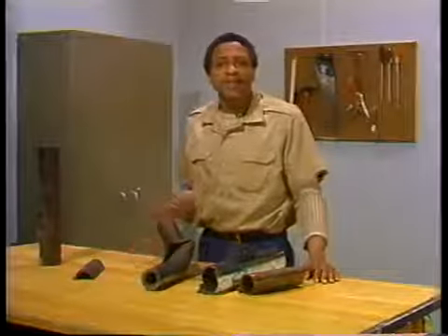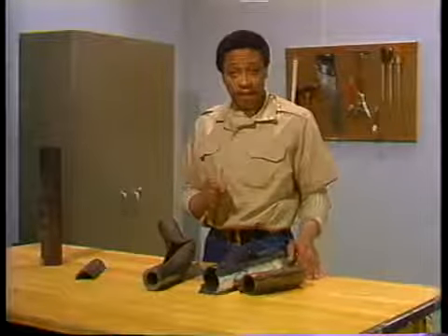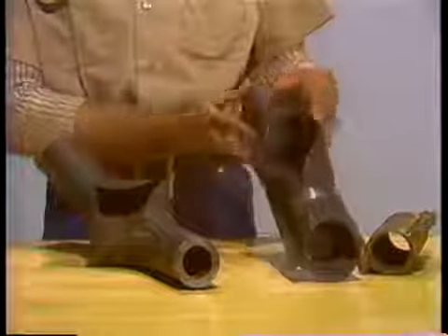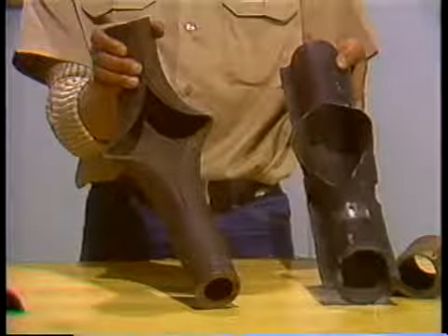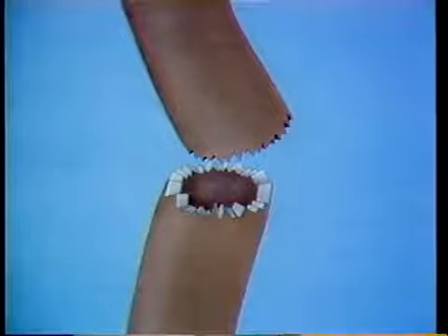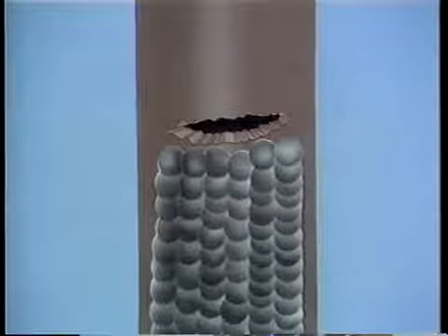We've now covered 9 common types of boiler tube failure. Thin-lipped ruptures, thick-lipped ruptures, double-ended ruptures, fatigue cracks, tearing of tube metal at support clips, tearing of tube metal at weld patches, thermal cracks, pinhole leaks, and steam gouging.